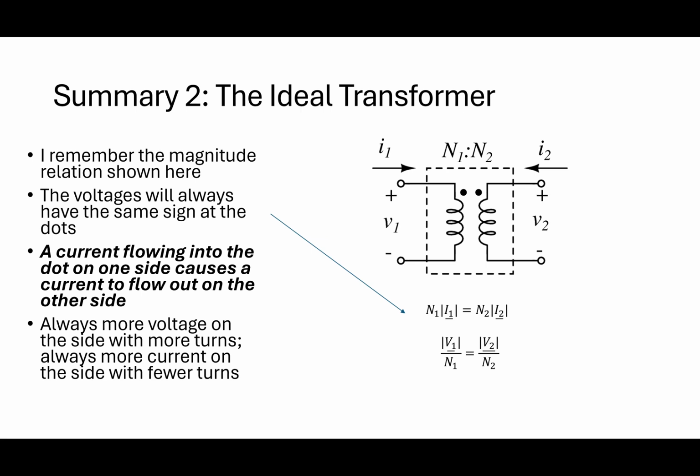The ideal transformer. What makes it ideal again? No leakage flux. That's the thing I'm really looking for. To get no leakage flux, what do I have to have? Permeability is basically infinite, which means the reluctance is basically zero. The directionality of the current could be whatever. We typically just do the directions of the current that way. That's just our standard approach for a two-port network.